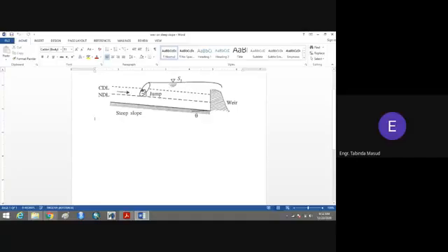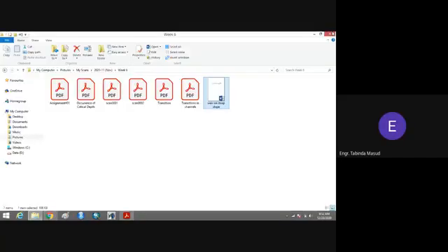In case of the subcritical flow, we discussed that when there is a flow in a channel over a weir, the depth of the flow will get decreased. But in a supercritical state, the depth of the flow gets increased. And here you can see that this was the depth of the flow in a channel, and now this is the depth of the flow over the weir.